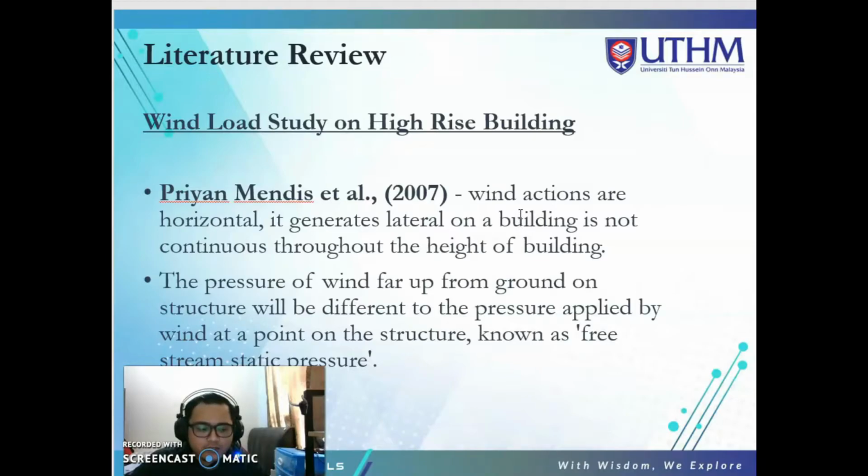Okay, so it rises with the height of the building because of the speed. It differs with height as the obstacles on the ground decrease its speed. So therefore, while analyzing a building, one should take care of the wind forces acting horizontally at different heights of the stories.